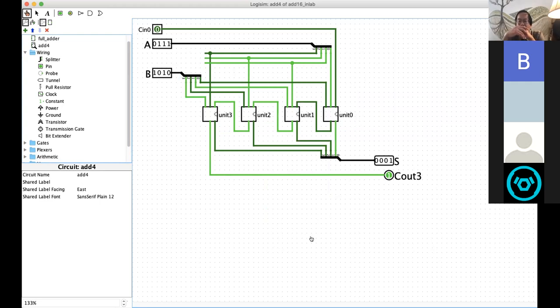I'm still having the problem where everything appears as an X. Everything appears as an X on the input? Okay. Let's take a look at your circuit. Click on the arrow here on the tool selection, and click on one of those pins. Do you get access? Yeah. Okay.